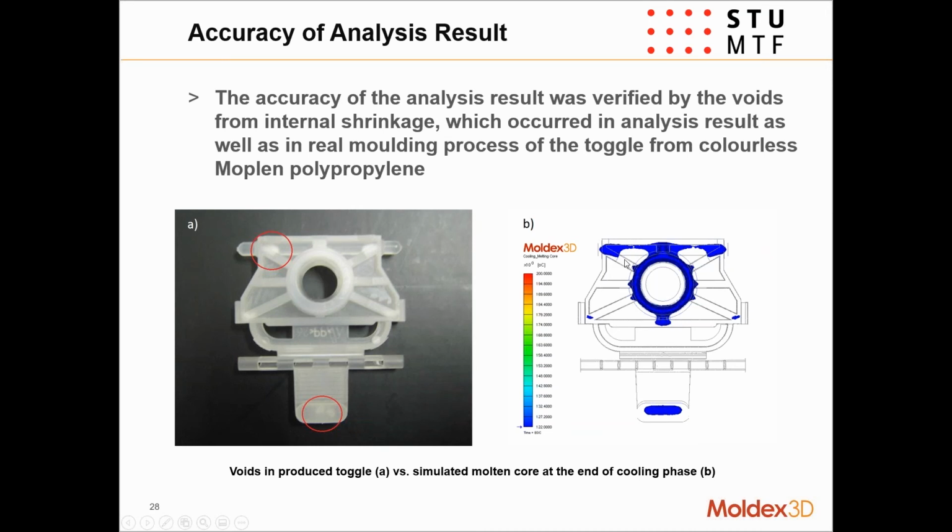So one of the things that GAIM can help us to do, if we can push air out into those regions, is reduce the thickness of the part there, which will reduce the likelihood of temperature being kept in that local hotspot. Being able to push material into these regions is going to help us reduce the likelihood of a void or even a sink mark or anything like that.